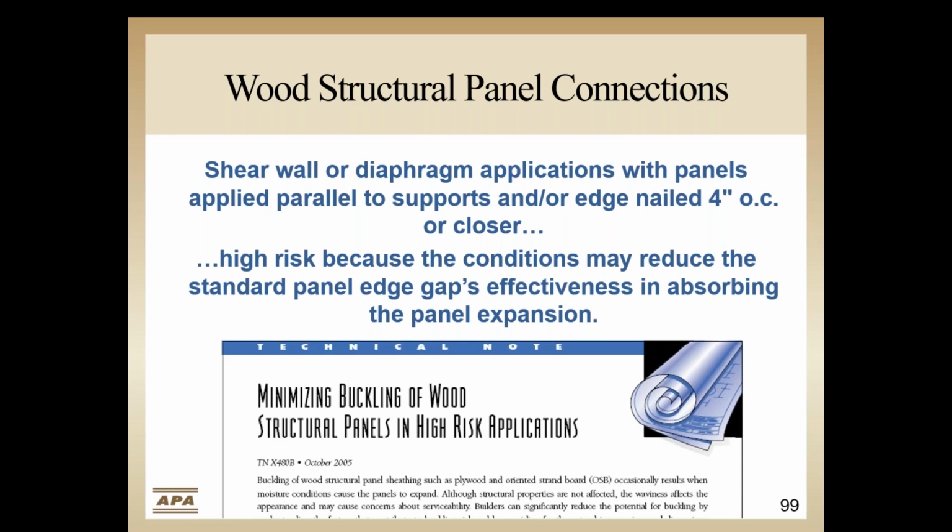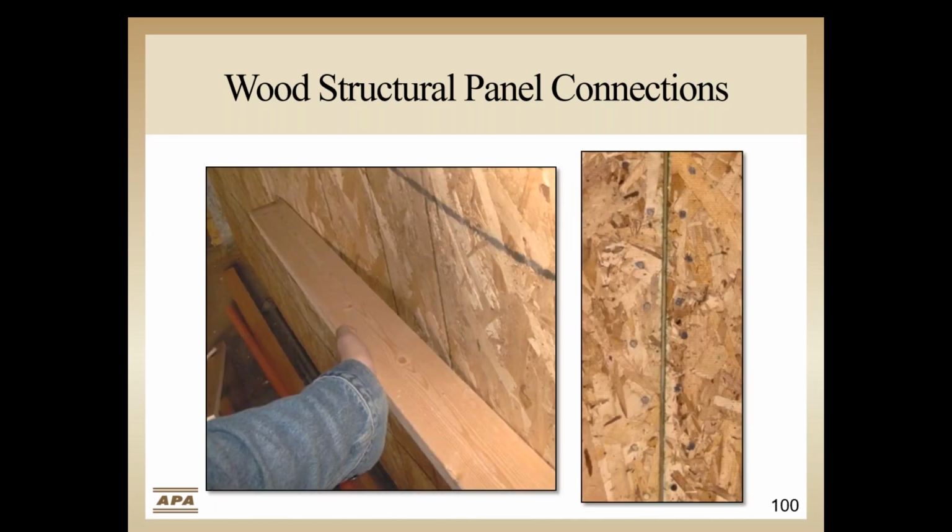The APA technical note on minimizing buckling of wood structural panels provides guidance in addressing these high-risk applications. These photos show good staggered nail spacing on the right and good panel gapping. However, they also show the buckling that can occur from panel expansion when restrained by the nailing and not allowing the 1/8 inch gap that is normally required to work.